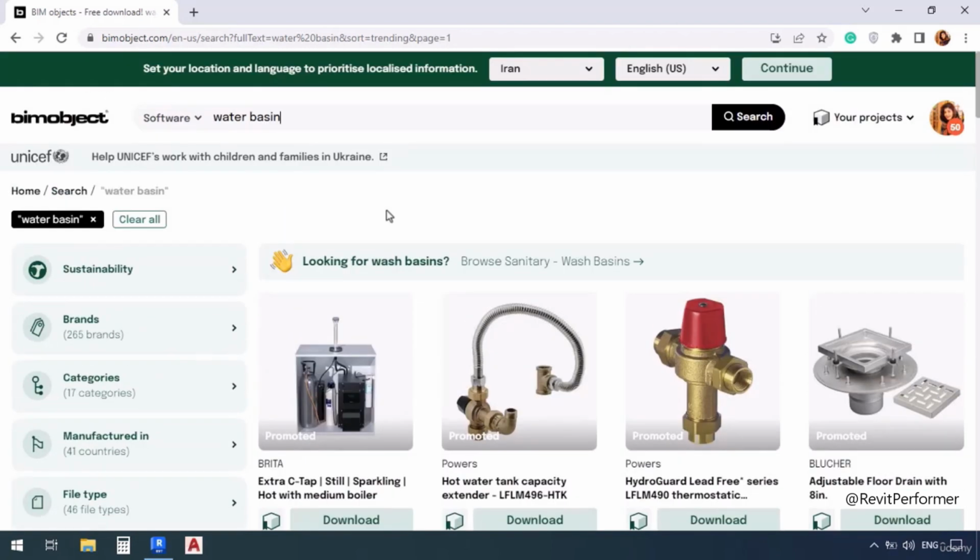So if you're looking for a family, you could go over here and search by a relevant keyword to find exactly the family you are looking for. Also, in case you are not very happy with where the connectors were located on your family, you could very easily edit and relocate them.